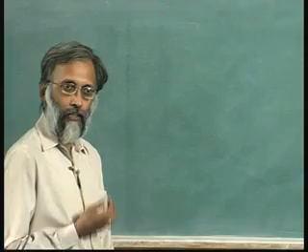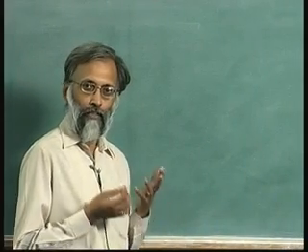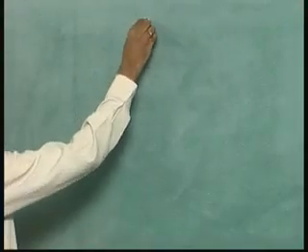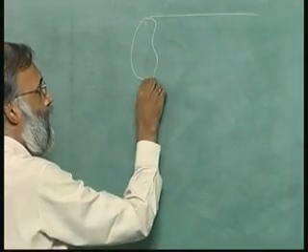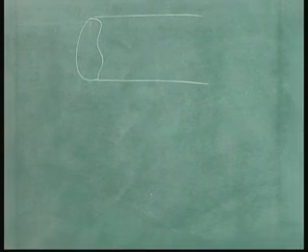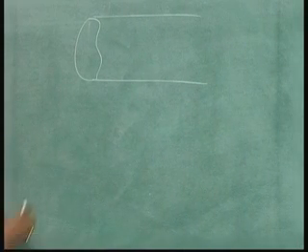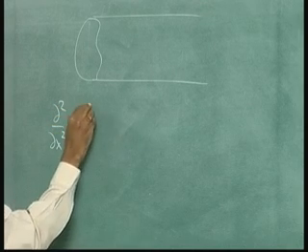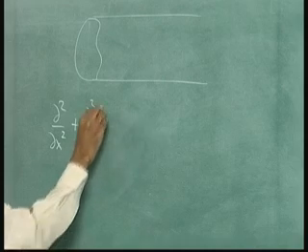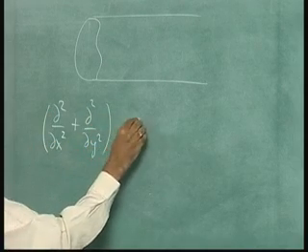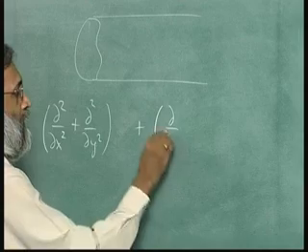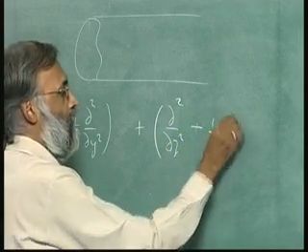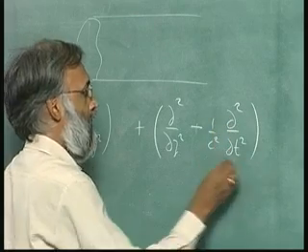And further, I talked about a special kind of wave inside a pipe which still looks like a plane wave. Namely, I have some cable and I look for a wave such that the x and y variations and the z and t variations decouple.